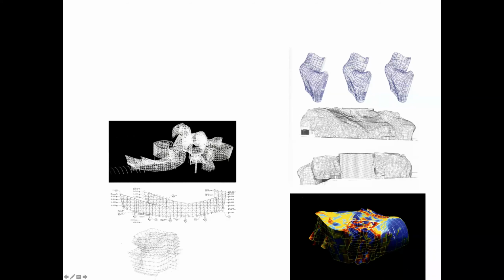Each time, what they can do is take a shape and look at the curvature analysis. And so they can take a look at this and go, well, the blue will only cost us this much because of the curvature involved here, right? This is a Gaussian curvature analysis. So the blue is mapped on there, orange is mapped on there, red is mapped on there. And so they can start to do at least some quick initial calculations, saying, well, all the blue areas, and they can get the amount of area that's shaded with blue, would cost $1 per square foot. And all the yellow areas would cost $5 per square foot. And all the red areas would cost $30 per square foot.